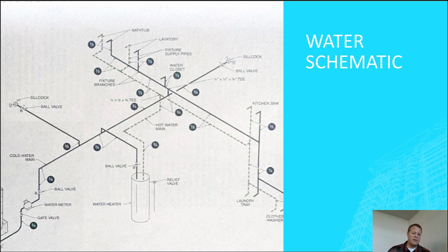And so we've got our water line coming in here. We have a little gate valve. We have a water meter. We have a ball valve. And they're saying 3/4 inch line. So we've got 3/4 inch coming over here.